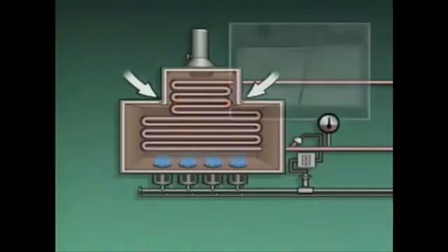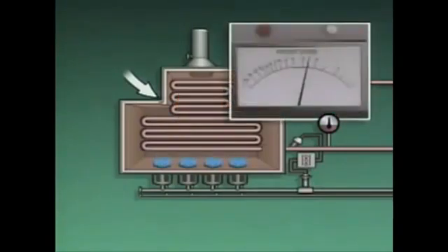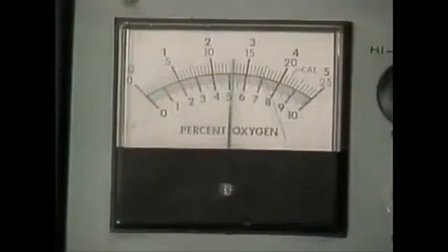An air leak can also throw off the excess air readings. For example, an air leak can cause the excess air value to increase. So a high excess air reading may mean that there's an air leak near where the reading's taken. Dark spots on the refractory could also be an indication of an air leak. Leaking air cools the refractory, making it appear darker than the hotter sections.